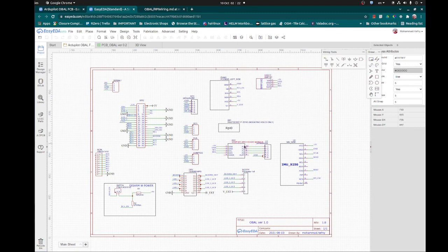So we have three devices connected via I2C, ADC, BMP, and PWM, and we have one SPI device, which is the IMU. We also have other ports for RC input, and we have ports for LEDs. We need to translate this to Ardupilot code so that when we compile this Ardupilot code and run it on Raspberry Pi, it will be able to control these sensors.